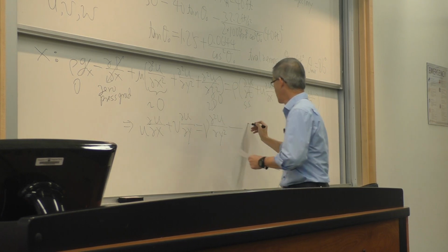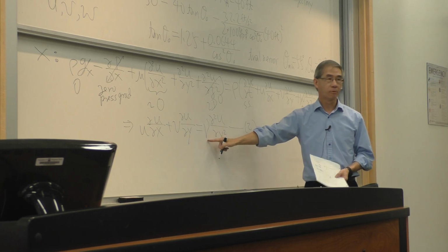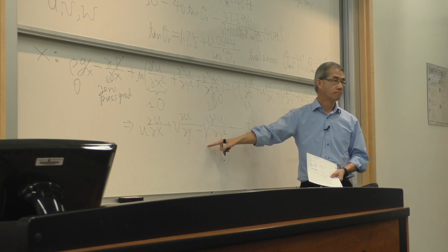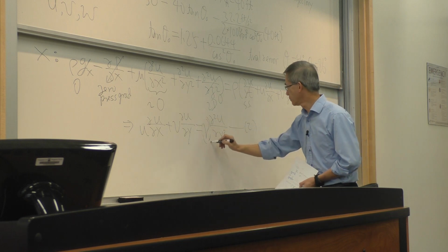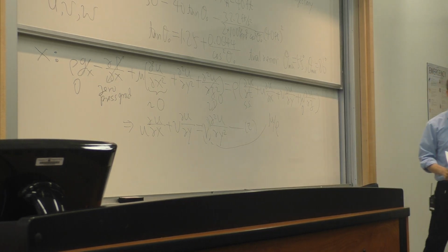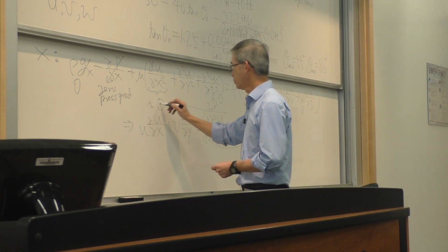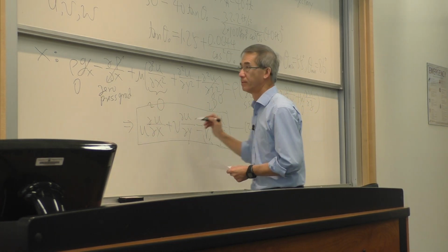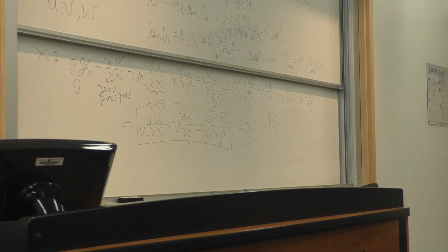The fact that that term disappeared, what's this symbol nu? Anyone remember? Kinematic viscosity was defined as the viscosity divided by density, so I just simplified that. So what is left are the two equations now shown in here: continuity, and the simplified momentum of Navier-Stokes by dropping that term that is approximately 0, and I apply the boundary condition.